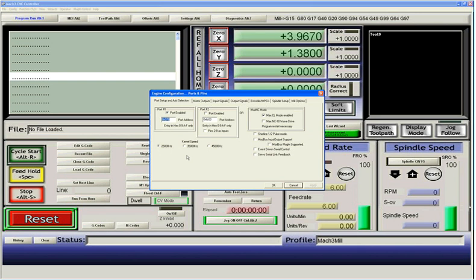It shows you how to check your control panel of your computer to make sure that the port address is proper for your computer. There's about 1 or 2% of computers out there which do not use 378 as their core address for a printer port. Some of them use C000 and some other PCI addresses. It's an unusual problem. The vast majority use 378, so it's probably not your problem.